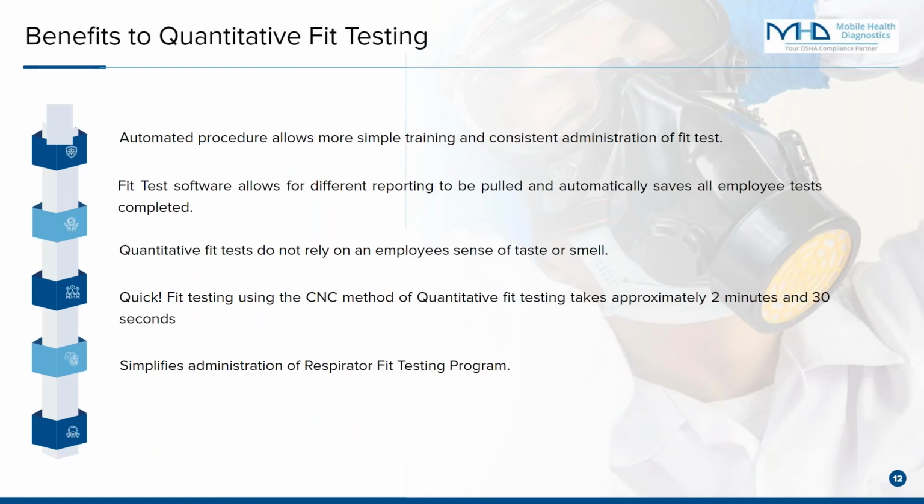So, benefits to quantitative fit testing. We already went through some of these, but basically it's an automated procedure and allows simpler training and consistent administration of fit tests. That's simple training both for the test taker and the person administering the test. Once a person's trained on how to use a PortaCount or a QuantiFit or an AccuFit 9000, that's it. There's not a ton of variety.